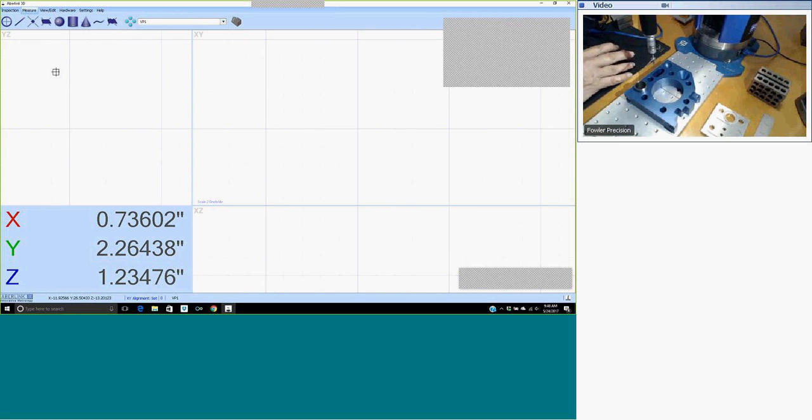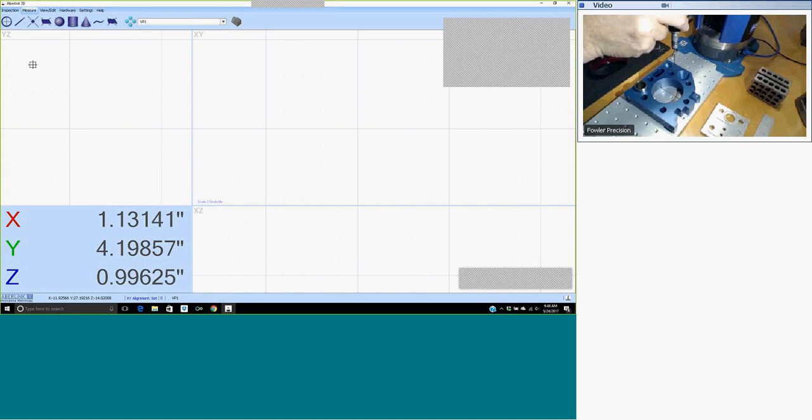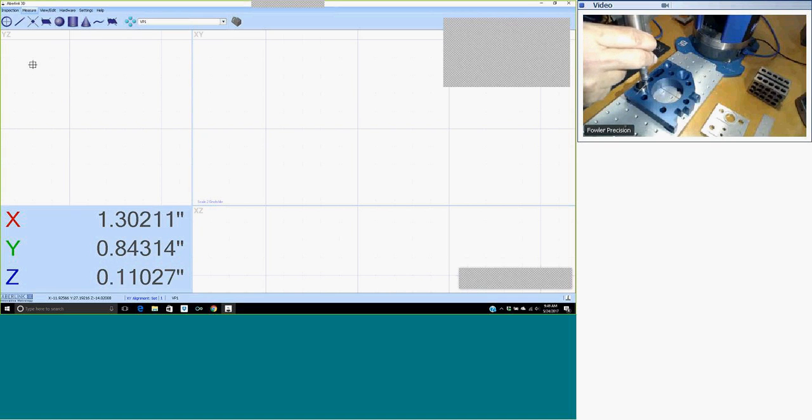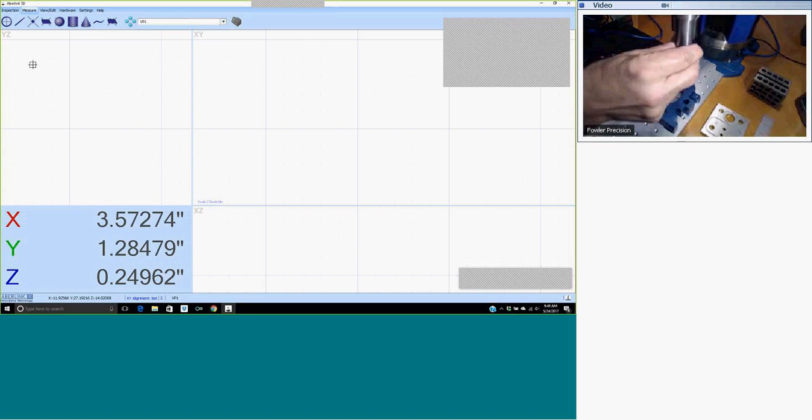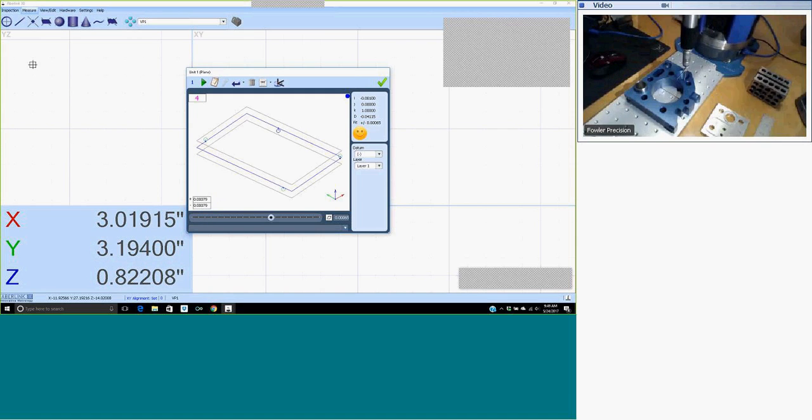So let's go into the measurement mode. And in my settings, I'm going to put it on feature predict and go to measure. With vertical preset for vertical 1, I'm just going to measure a plane on the top of the part. At my fourth point, you'll see it comes up and measures that as a plane.